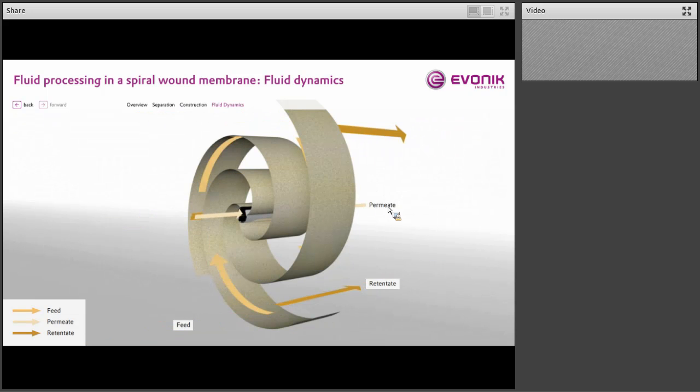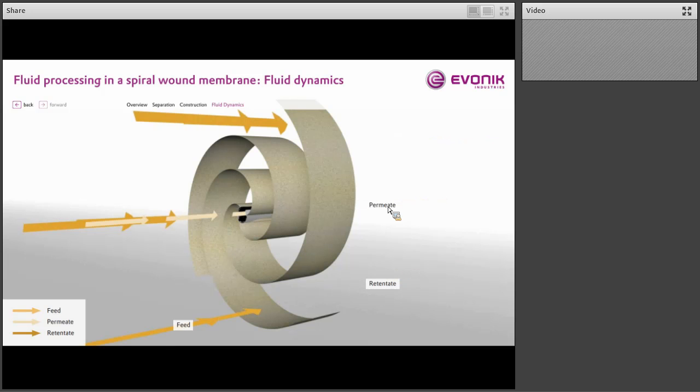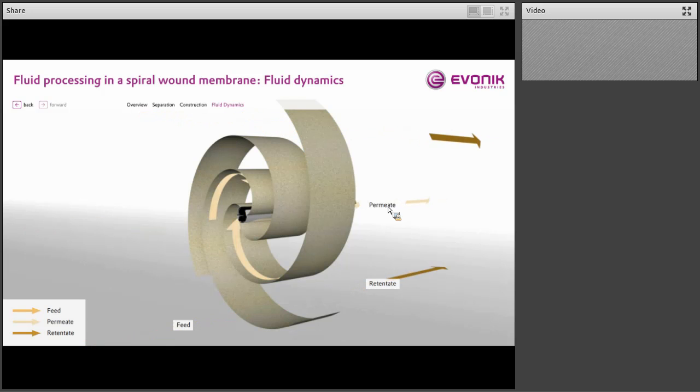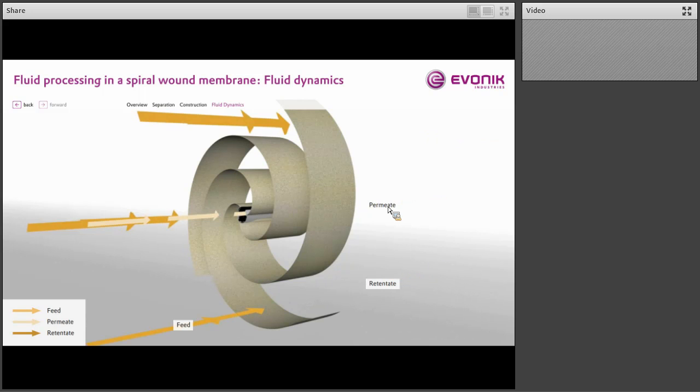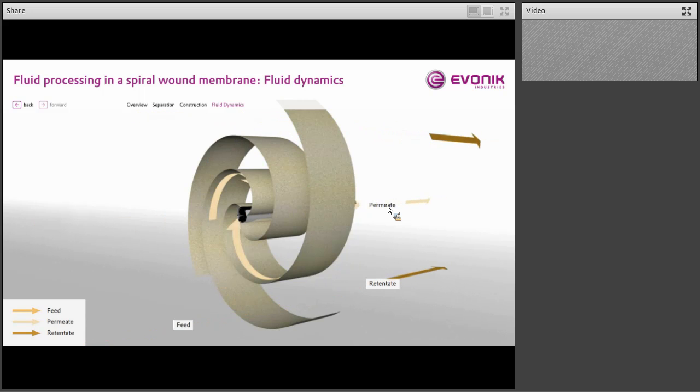So you can imagine it as a Swiss roll, where the process fluid is passing down where the jam goes in the Swiss roll. The fluid that you are collecting, the permeate, is going into inside of the sponge and coming around to the middle of the Swiss roll and flowing out. So this is the most common type of membrane module that is used in liquid separations.